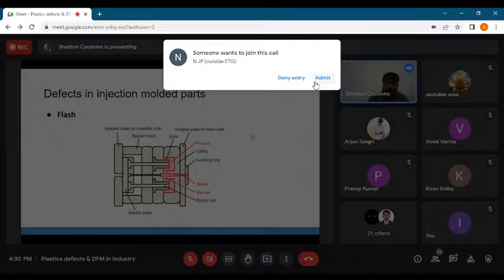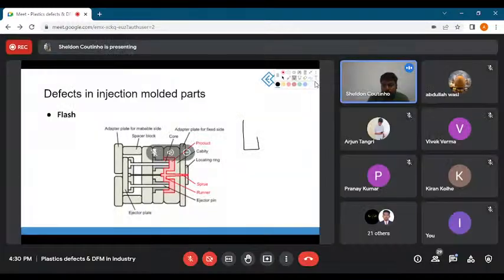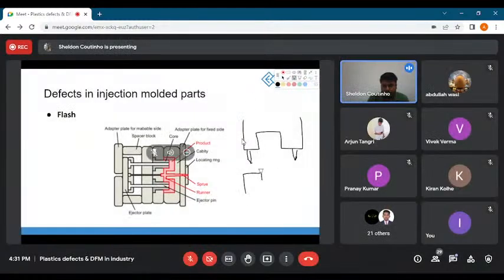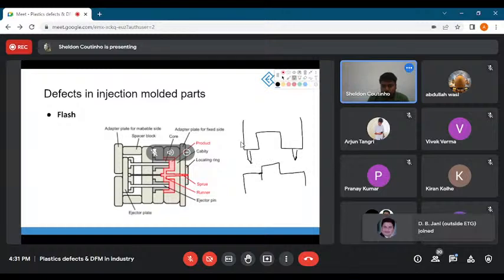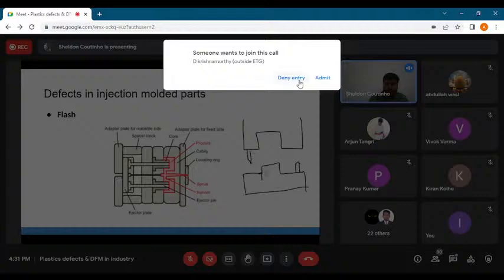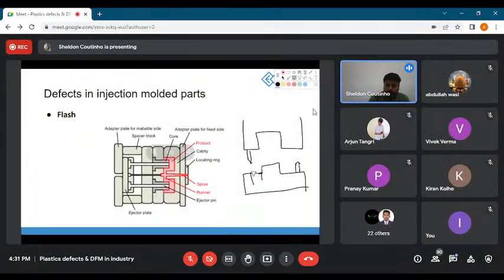These are completely different. In molds, if this is the core side of your mold, for example, you will have a locator pin out here, which will be tapered to a certain degree, and on the other side as well. These pins are also made out of really hard materials. And on the other side, you will have some holes, and this could be varied. It's not necessary that it is like this. This could be made like this as well. You could have locators on both your plates, on the core side as well as the cavity side, and this will penetrate into the mold.